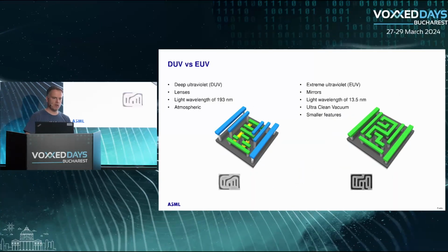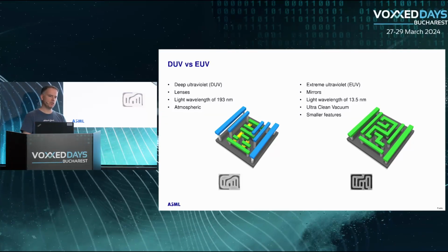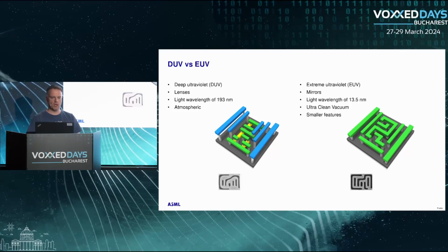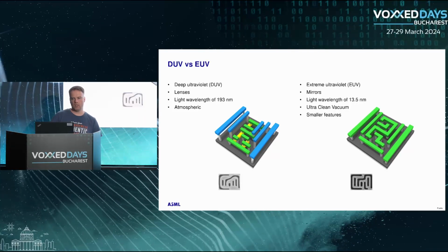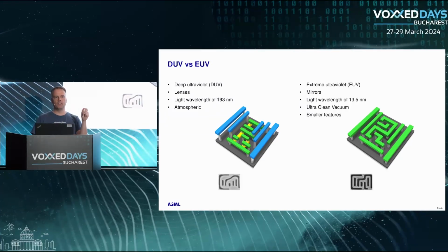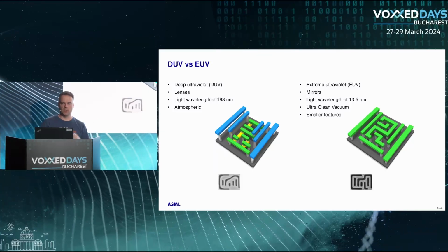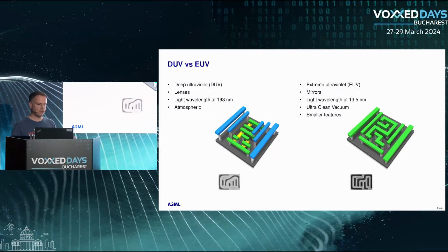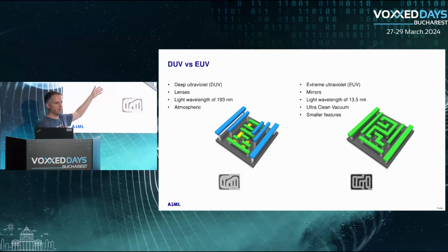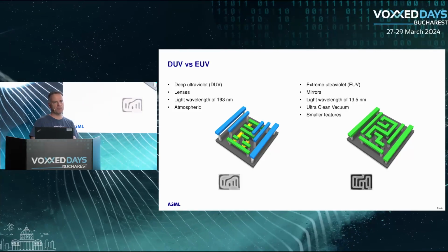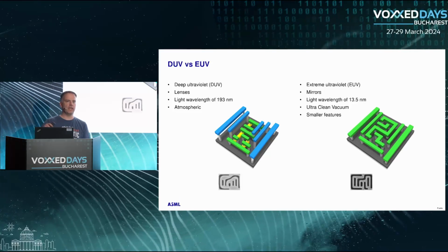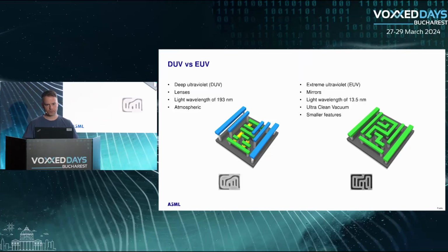And then a bit about what state we're currently in. Nowadays, the advanced machines use EUV technology, which I just explained. The older machines use DUV. The biggest difference between those generations of machines is how small a detail can be printed. Each new machine can print smaller detail. For example, with DUV, you see that something requires several layers to add a feature. With EUV we can print that feature in one layer. That's of course quicker, since you only need to do that layer once instead of multiple times.